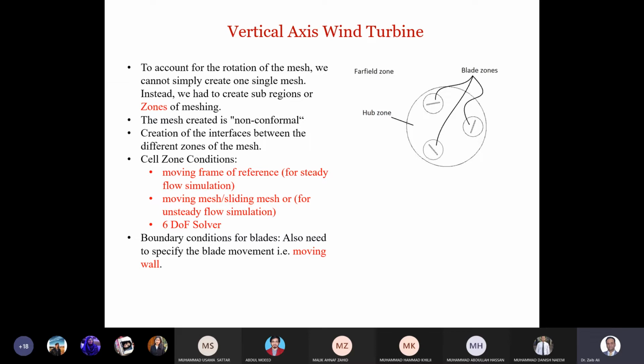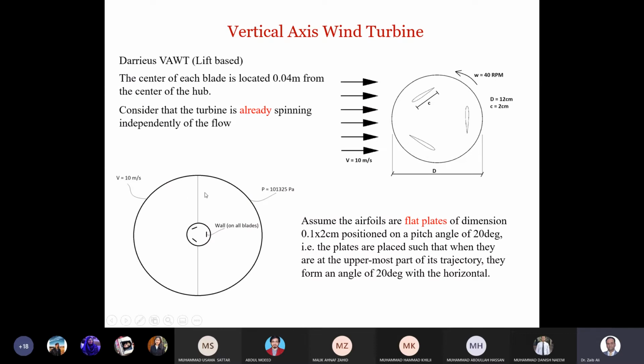Okay, so what options do we have in Fluent to simulate such a problem? First major difference you should observe is that in here we have some zones which are moving, and some parts which should be static. Like this far field should be a stationary part because it's a far field containing our inlet and outlet conditions.